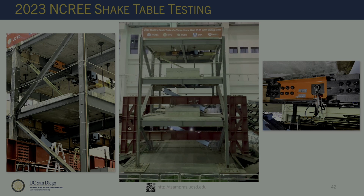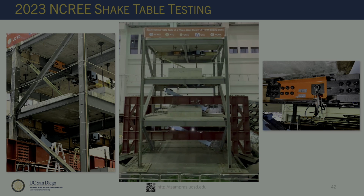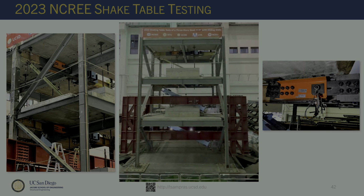Yeah. In Tainan. So this is a friction device connecting the floor diaphragm with a steel moment frame, and you may see some sliding up on the top floor there. So that cost around $400, I guess, to make. And the last piece is repairability, I guess. I put an asterisk next to it because there are some designs that are easily repairable, some other not, if it comes up.